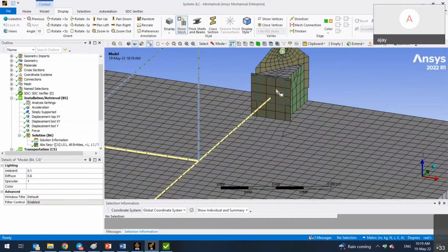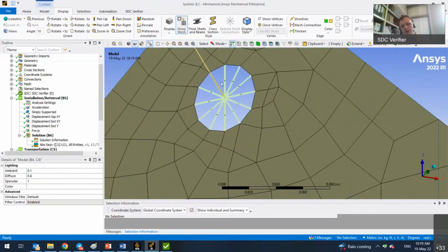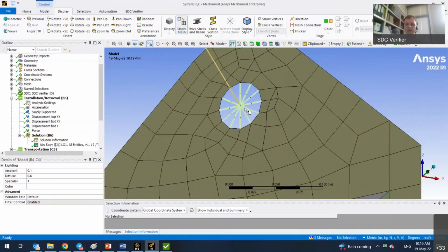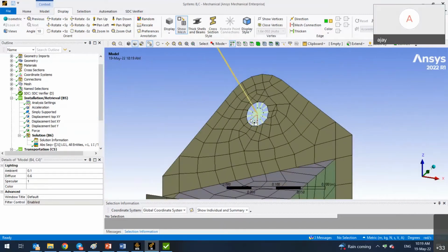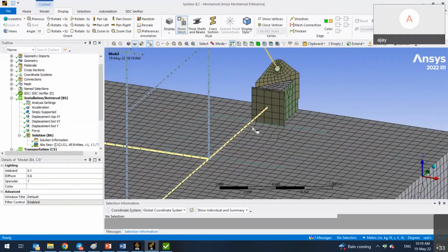I haven't paid that much attention to this. In this case, it's a contact, and in this case, we connect it with the rigid body elements, which has allowed all rotations on the end. So it simulates the pin. And how about this all along the beam, the connection between the shell and the beam all along?